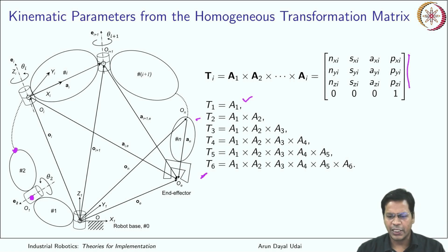If it is for the sixth link, let us say this is a 6 degrees of freedom robot, it will give you the position of, I assume this also includes the tool, all the end effector dimensions, because it is permanently mounted without any joint at the end of the last link. So if that is included, this is your position that will be given by T6. Got it? So 1, 2, 3, 4, 5, 6. At the end of the 6th link, you get this position.